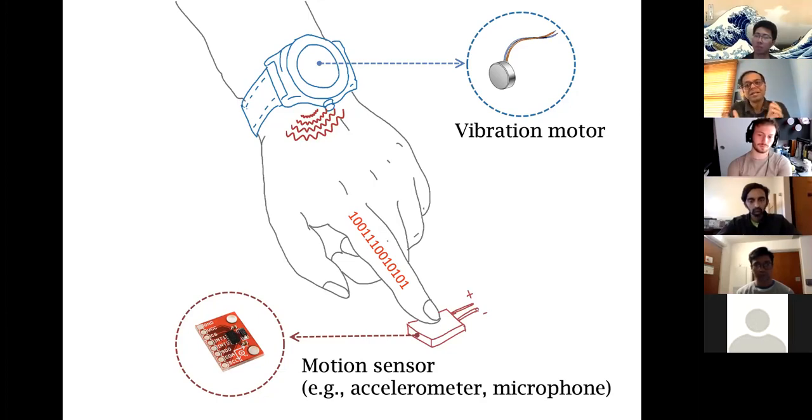So you might say, I want a few frequencies to embody one data bit so that I have some averaging effect for noise. So now it's a design question. How can you push the data rate for vibratory communication, given that your receiver is an accelerometer?